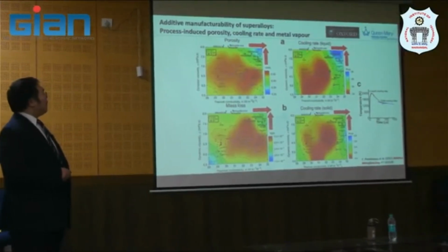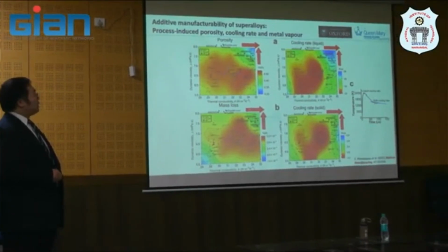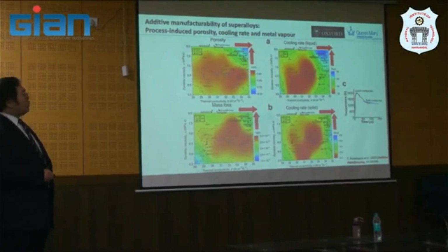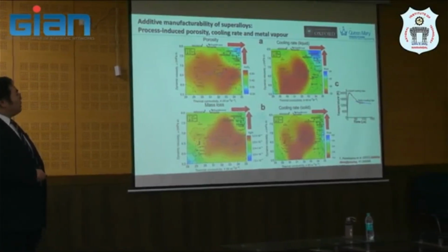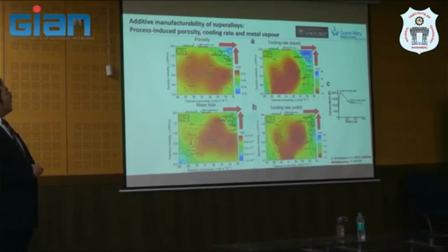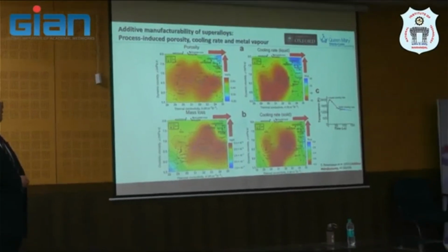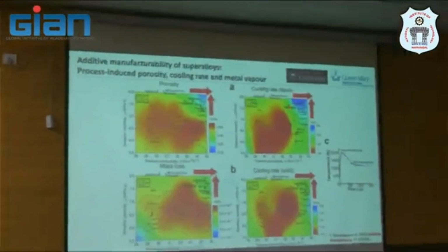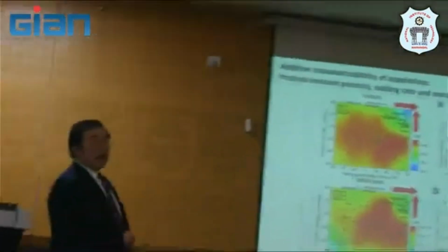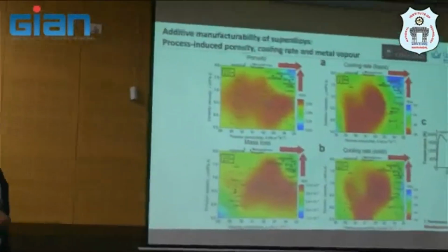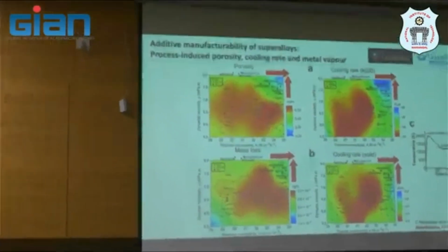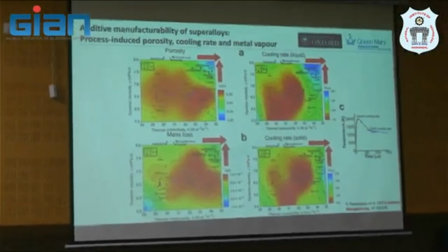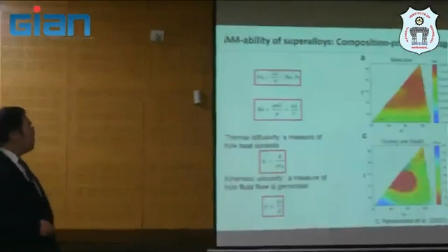So in this case, we have liquid and solid, which contribute to distortion, for example. And then this is a sweet spot where we can select some property in this window. And you know, I actually mapped the printable nickel-based superalloys as well. It matches quite well with this kind of CFD-based process design approach here.